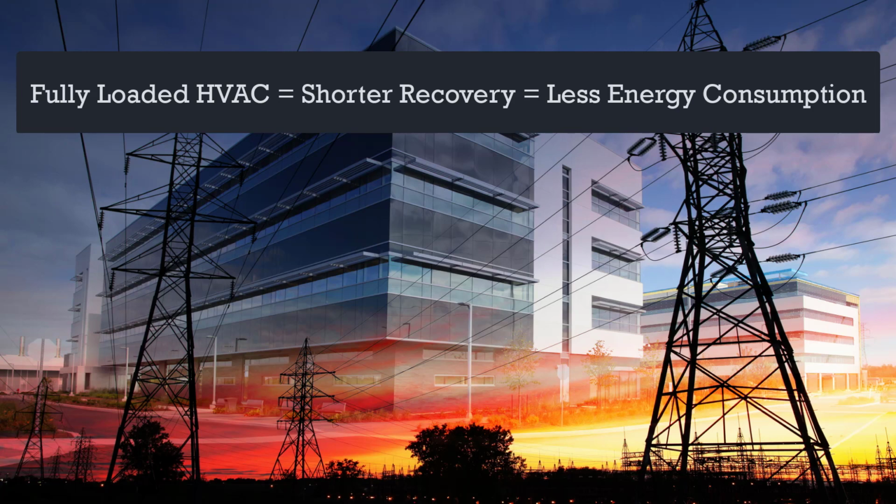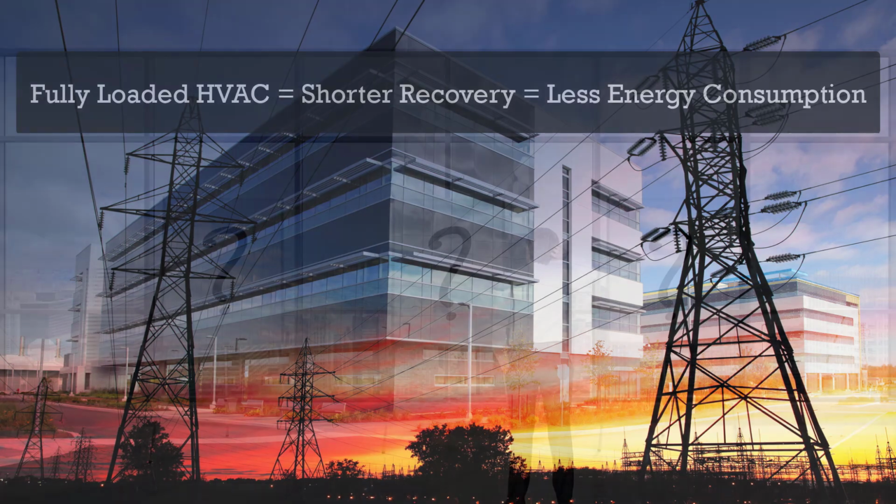Recovery time and duration of HVAC equipment operation and related electricity and thermal consumption is directly related to the HVAC load during the morning cool-down cycle. Successful optimum start cooling strategies fully load HVAC equipment to remove heat faster, achieving the shortest recovery time. This practice will result in less energy consumed over a shorter period of time.